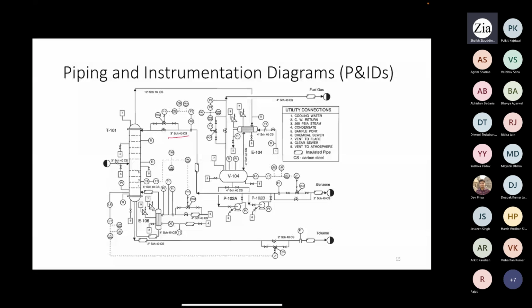Whenever it compares with the set value, it will sense whether it has to activate the alkali dosing pump or the acid dosing pump. Whenever pH is more than neutral pH, it will try to neutralize, so it will start adding acid. And whenever it senses lower pH than the neutral level, it will start adding a certain amount of alkali, and then again monitor the pH to check whether it is actually maintained at neutral level.